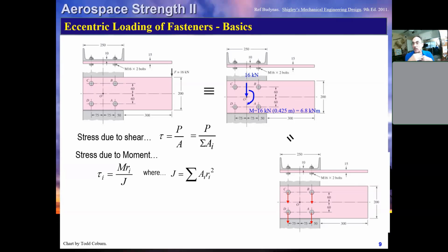And it's going to be perpendicular, going back to statics, lecture 5 or whatever. We found out that R cross F equals moment. So actually, we're going to get a component that's perpendicular to the radial arm from the centroid to each fastener pattern center. The torsional constant is just the area of each fastener times the R. We're going to pretend that each fastener really has no moment of inertia about its own axis because that plate can just slide around that round fastener.